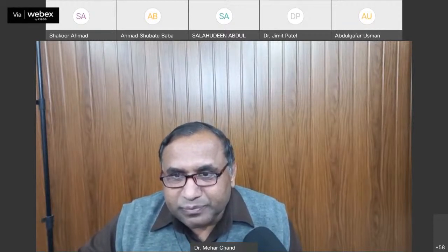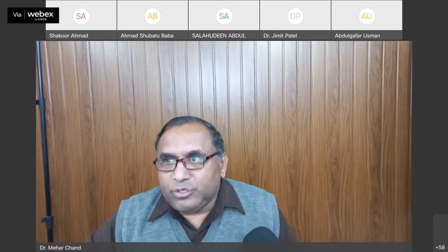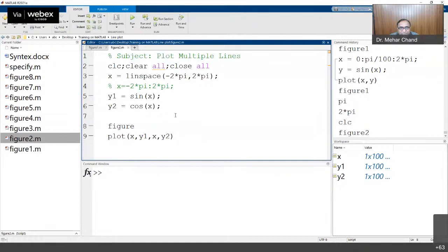Now again, see. So you can see multiple graphs are there. Also, see here, when we are not using linspace, by Control+R we can comment the line. And when we comment any statement, that particular statement will not execute. So you can see, I commented this statement by pressing Control+R. Okay.